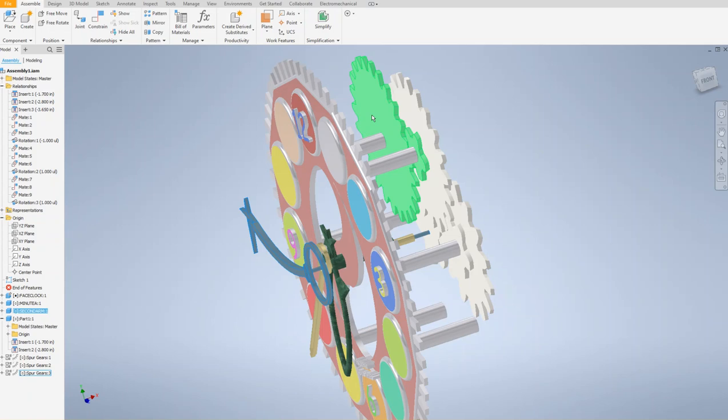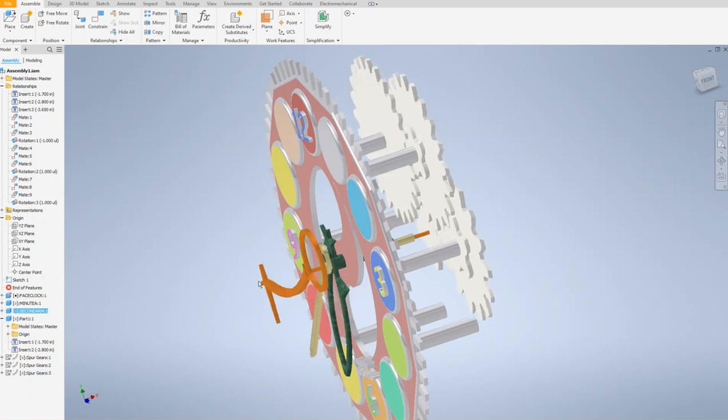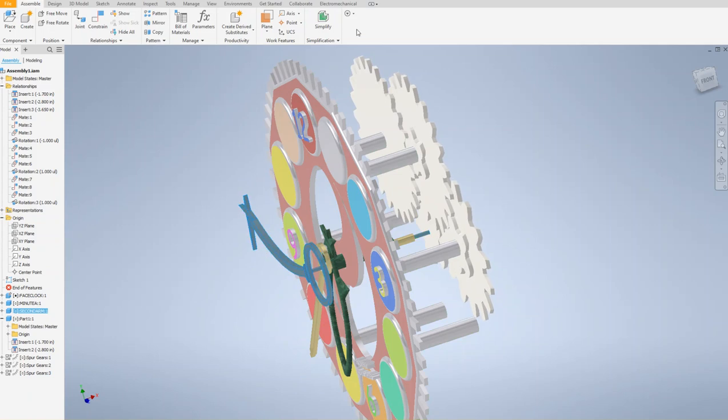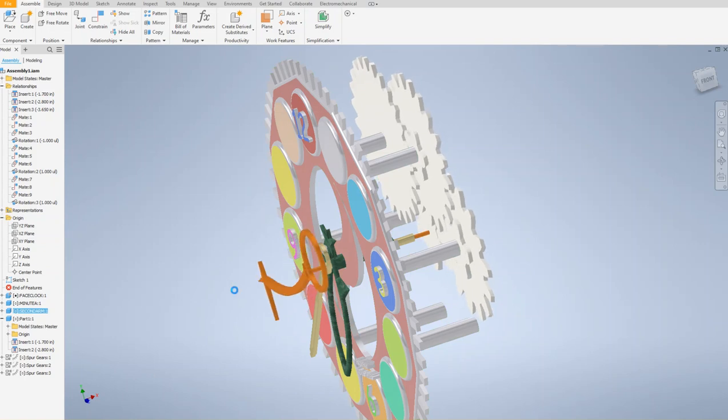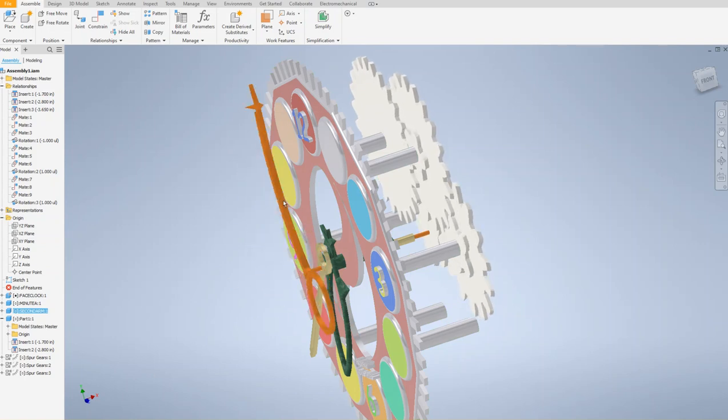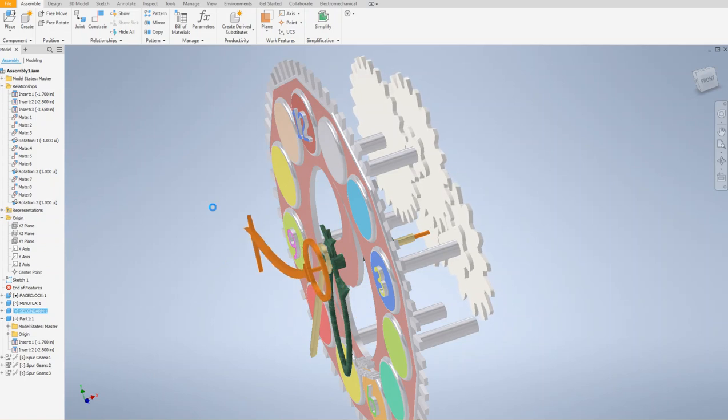We're supposed to directly relate this to the minute arm. Minute arm gears are going to be separate, but I have to connect this large gear right now to the minute arm in a fashion that corrects the counterclockwise motion. As you can see, everything turns correctly in a clockwise fashion, but the large gear rotates in a counterclockwise fashion.